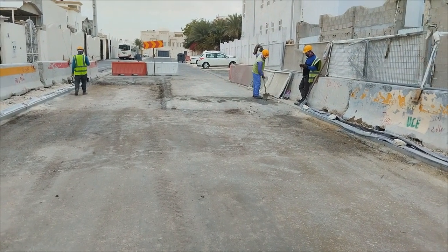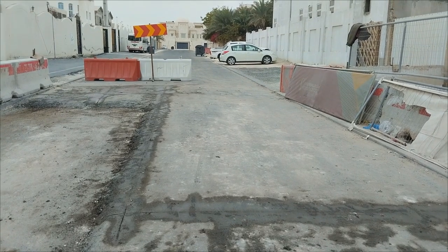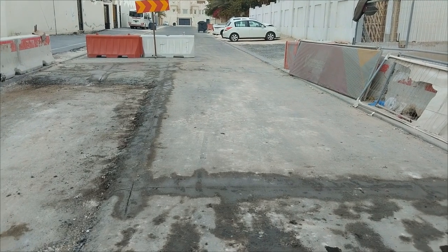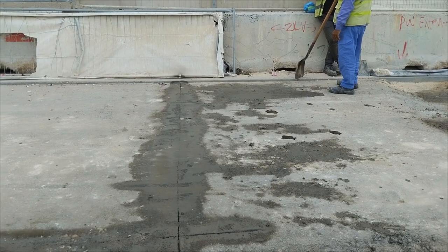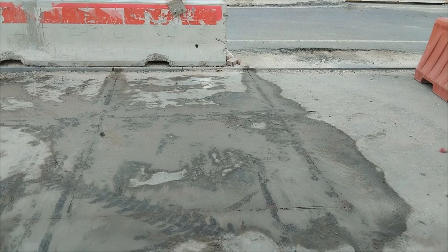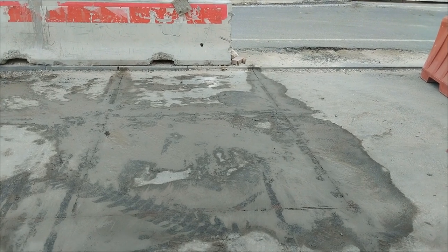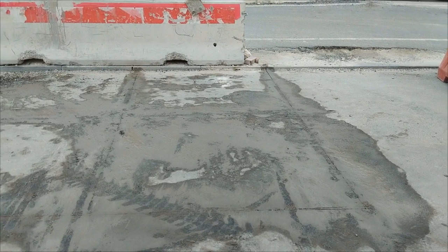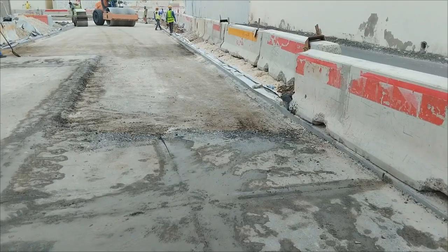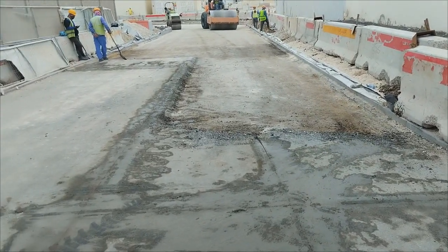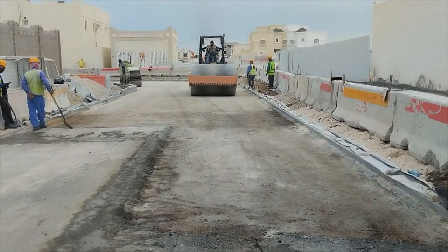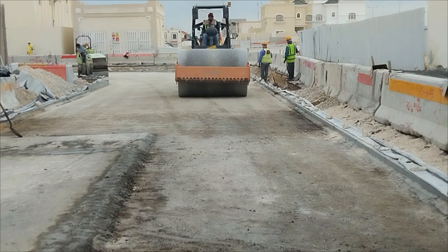I will show you now, the asphalt cut joint is already cut. But the next activities will proceed maybe after 2 days. We will proceed for the asphalt. So the asphalt joint is cut in advance, and the joint should be cut transversely with 2 meter staggered joints. This asphalt joint will be removed and tied with the new asphalt, which we have planned for the next 2 days.